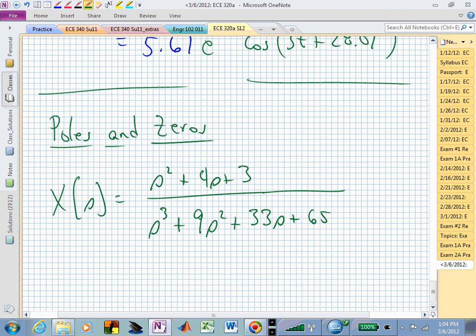It's third order because that's the number of poles we have. And if we have a third order circuit, how many energy storage devices do we have? If we have a passive circuit, we have 3 energy storage devices. We could have a couple of inductors and a capacitor. We could have 3 capacitors. And this is what you could be telling the person that was interviewing you.